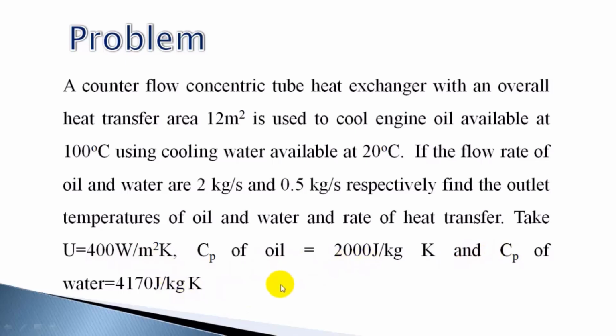Now in this case you can easily see that NTU approach is going to be easy for us because outlet temperatures of both the fluids are not known. So LMTD method becomes tedious.